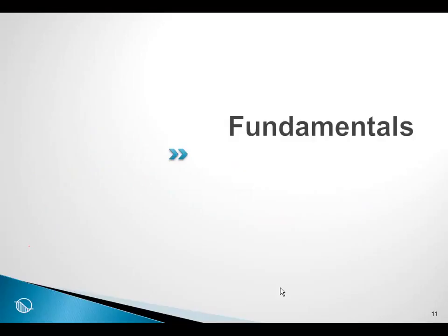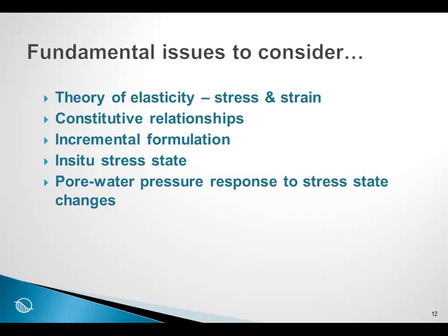Moving on then to some of the sigma W fundamentals. To begin with, there is the theory of elasticity, that is, stress and strain. Sigma W is based on the fundamentals of the theory of elasticity. There are several different types of constitutive relationships. Sigma W is formulated on the basis of an incremental formulation, which is very important to understand to use sigma W effectively.